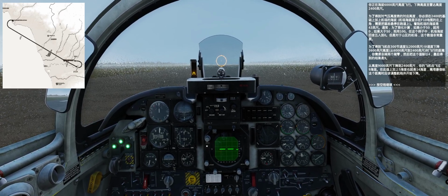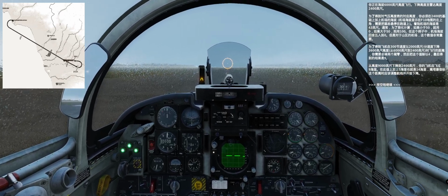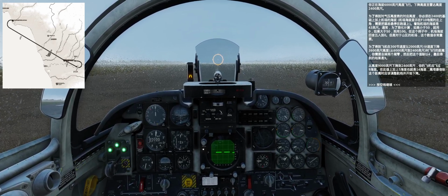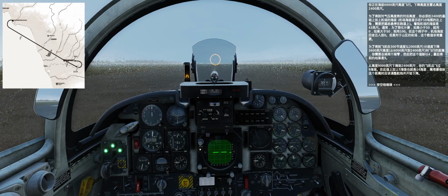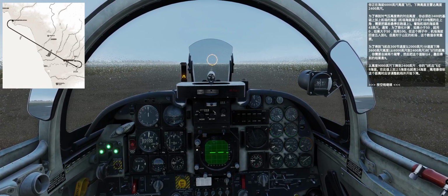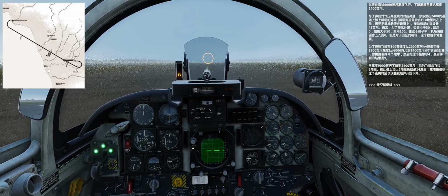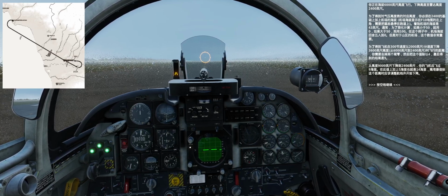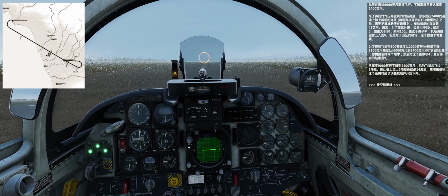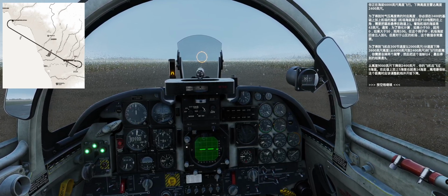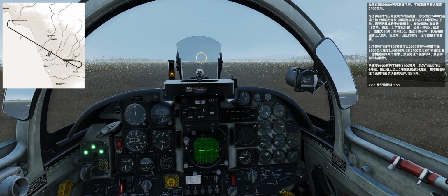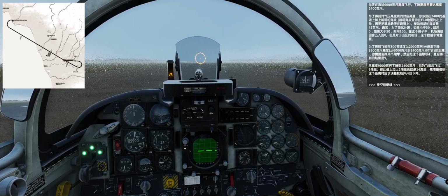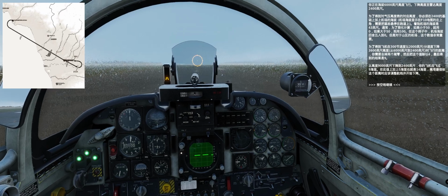To determine the distance the aircraft covers flying at 300 knots and descending 3,600 feet with a vertical speed of 2,000 feet per minute, we must discard 2 trailing zeros and divide the received number by 4. The result equals 9. The aircraft covers 9 nautical miles when descending from an altitude of 6,000 feet to a landing pattern altitude of 2,400 feet. Add 5 miles to this value needed for changing the desired course and start descending at 14 miles from TACAN beacon. Press space to continue.